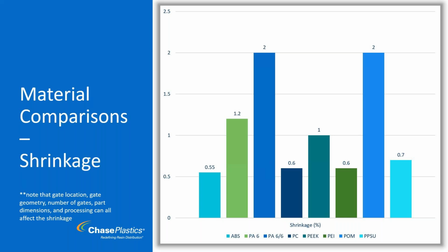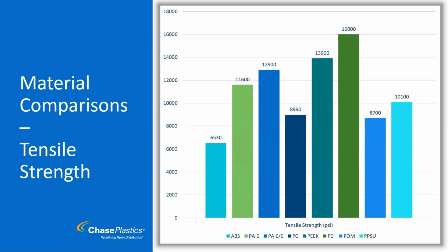And then the ones with your higher shrinkage values, semicrystalline, they shrink more. So we have a nylon 6, a nylon 6,6, a PEEK, and an acetal. And so you can see different shrinkage all the way across the board with 6,6 and acetal shrinking the most at unfilled 2% shrinkage. Okay. So big distinction there, big difference there.